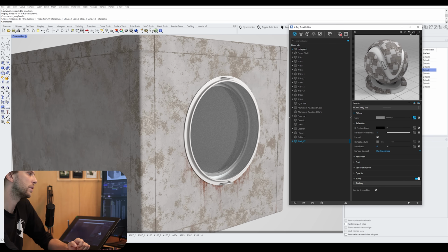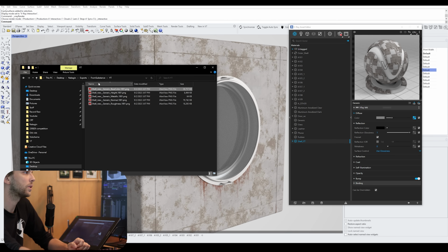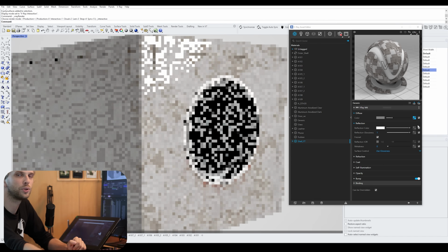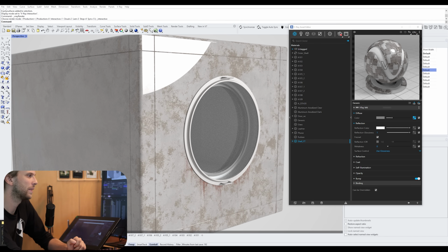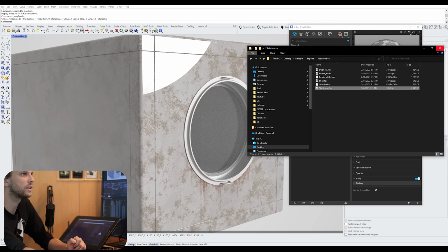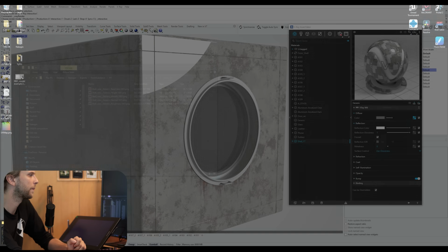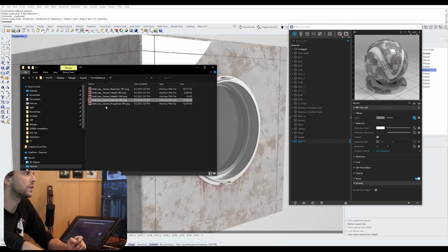So we're going for a metallic. There we go. We're going for the metallic route of defining the material. So that means we're gonna be dealing with roughness, metallic, right? These two define what's glossy, what's not. In those kind of instances, the reflection color is always set to pure white, like that. It's super glossy right now. And then we go for, well, let me just close that so that it's not annoying. And then we go for the roughness.